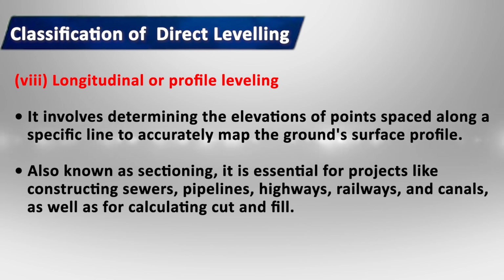These readings along with chainage are recorded in the level book. The method provides crucial data for comparing different route options and includes noting features like stream beds, roads and culverts along the section line.